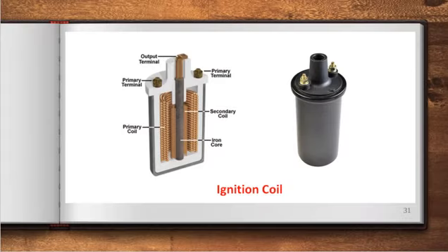Next one is the ignition coil. Vehicle electrical components like ignition coil, primary and secondary windings have specified resistance data, but tolerance is also given. It means that when the resistance reading is above or below the standard reading, but within the limits of its tolerance, it is said that the resistance is acceptable or tolerable. And you can only find that in the manual.